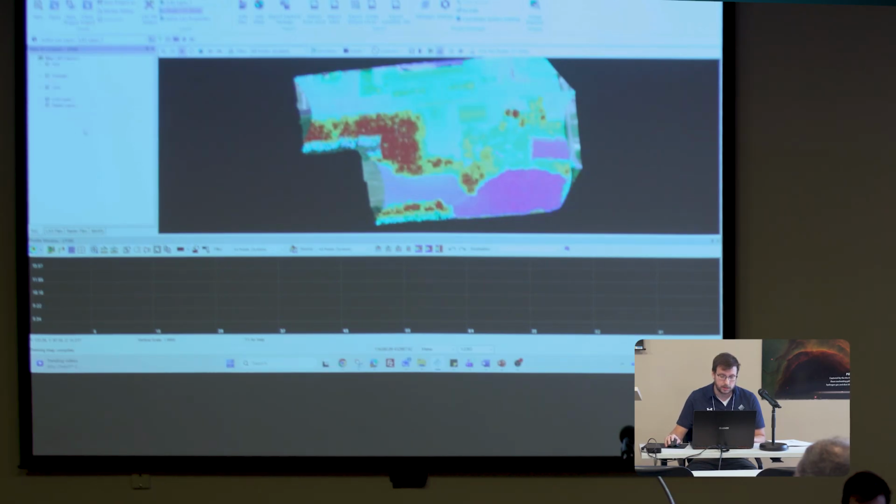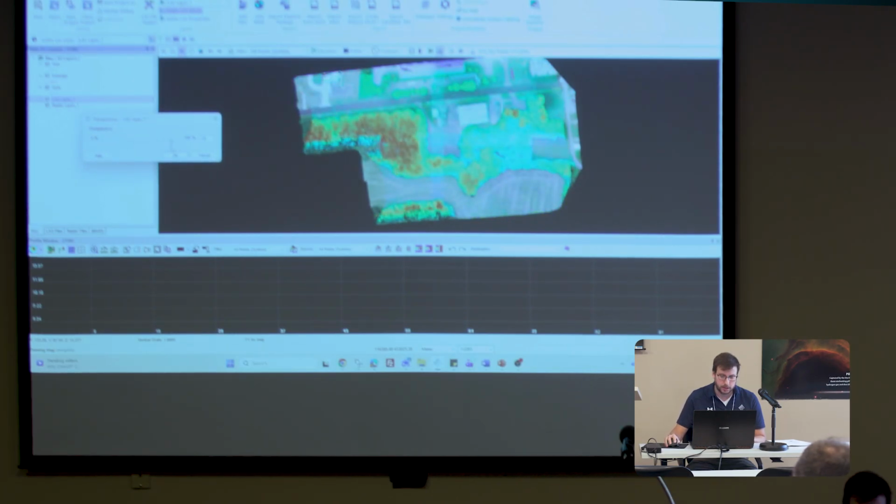And I can move it back down. So I'm just letting you know you can play with that. One other thing, kind of an Easter egg that a lot of people don't know about. Right click. You can follow along with me if you want, but right click on the LAS layer, go to transparency. There's an option for transparency, and we can actually adjust the transparency of the LAS with the ortho.